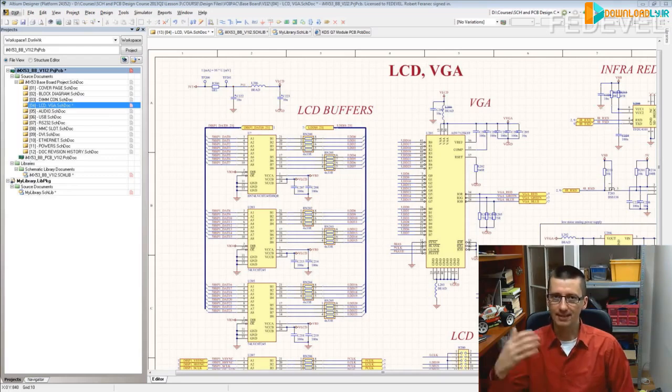Because in my next design, I was still not convinced. So what I've done, instead of placing one resistor on the gap, I provided the option to place more resistors around the gap. When all the 0 ohm resistors were fitted, I somehow simulated the ground connection around the island.